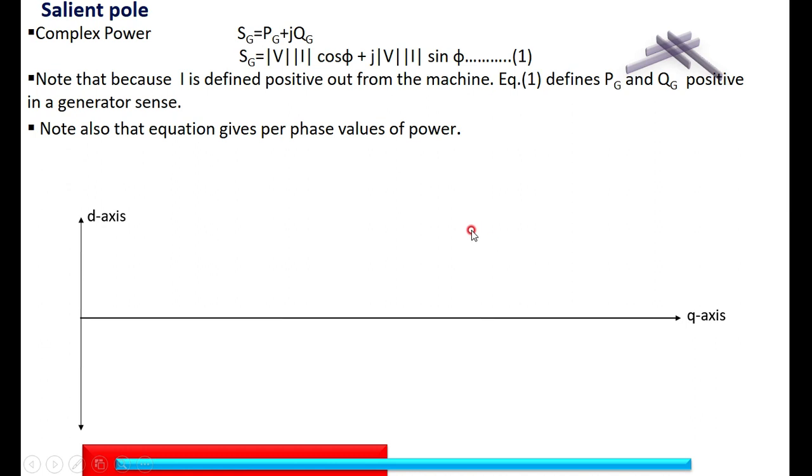We'll start drawing the vector diagram, taking the terminal voltage, load current and the power factor. You can take the phasor of V arbitrarily. Then I am considering a lagging power factor, so I lags V by an angle phi. Therefore, I draw the vector I lagging V, because I consider this vector diagram for a lagging power factor.